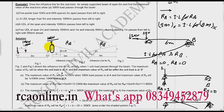Now take the second case. When will be the maximum value of RB? The maximum value of RB will again be 1 multiplied by 10, which is 10. And when will this happen? When the load is at B. So RB has its maximum value when the 10 kilonewton load is at point B. RA will have its maximum value when the 10 kilonewton load is at point A.